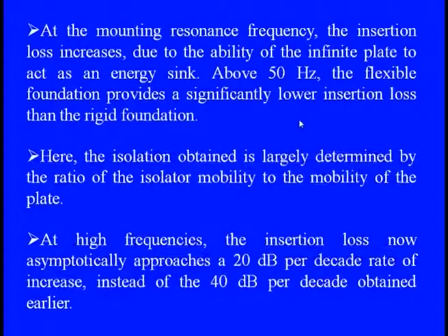So at the mounting resonances, whatever the frequencies are there, the insertion losses increase due to the ability of the infinite plate to act as a more sink of energy. That means whatever the exciting frequencies of the mounting resonances, the insertion losses always become more significant.